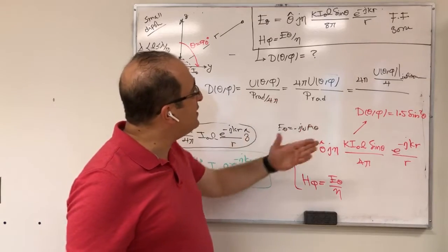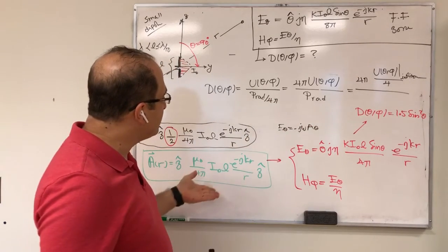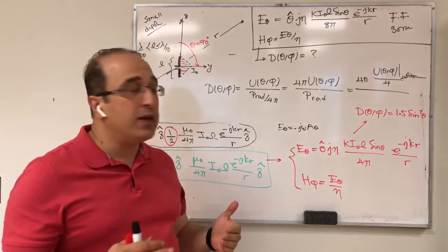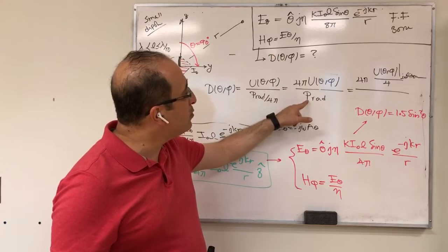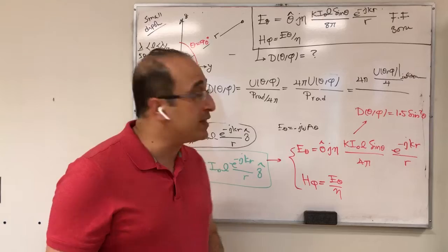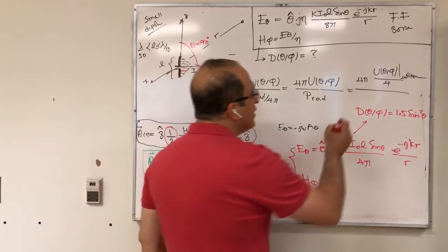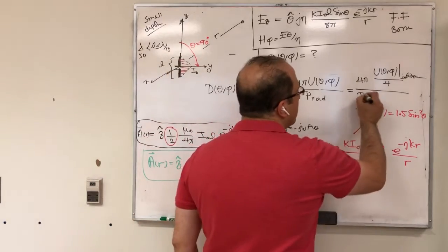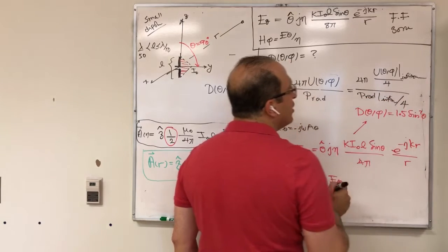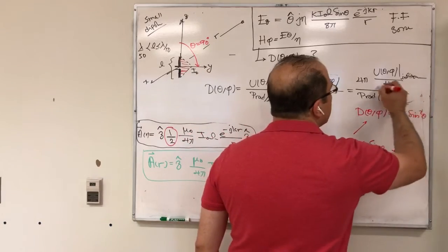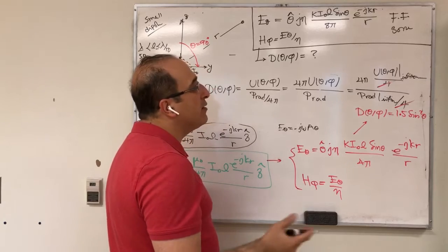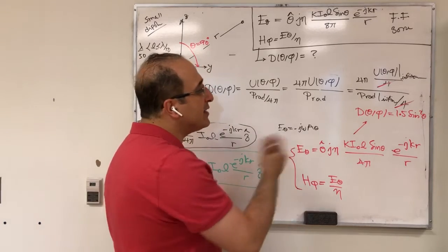So the power radiated by this antenna, in terms of mathematical expression, would be, for a small dipole antenna, P rad of infinitesimal divided by 4, because power is also related to E times H. So these cancel, and now I have just infinitesimal, therefore I'm going to get exactly the same directivity.